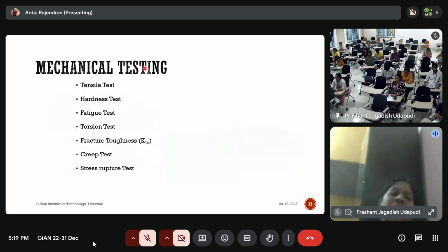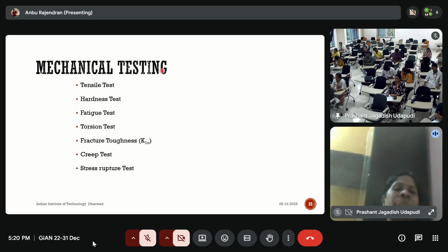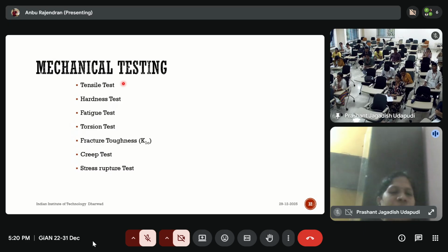Yeah. So as I mentioned, all those methods come under microstructure analysis, part of destructive analysis. Another testing method is mechanical testing, where you can measure the mechanical properties of the component. Okay, this is also destructive testing because at the end of the test you are damaging the sample. For mechanical testing, you may be aware of the tensile test, hardness test, fatigue, and additional special tests for a particular application, right? Everyone must have done tensile and hardness tests in your lab for any samples you are working on, right?